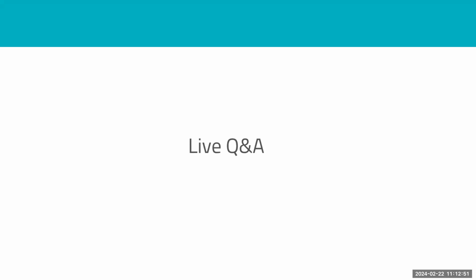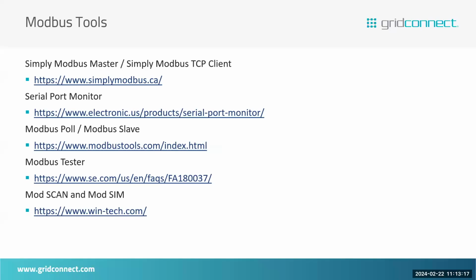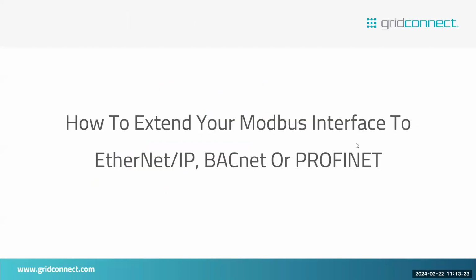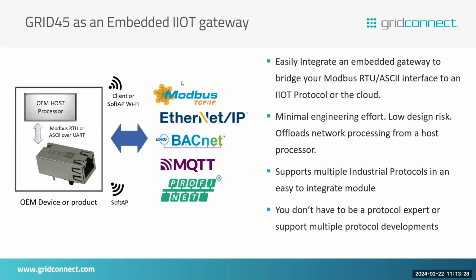And by a generic gateway, it means that it already has a GSD file, and you have to conform your Modbus data into how the GSD file is laid out. I don't know if that's clear or not, but if you move the gateway into your product, like we showed on one of the slides as an embedded gateway, then now you are making the device. If you're an OEM trying to create a Profinet device and you already have Modbus, you can create a Profinet device in that way. You still have to have your device certified and such.